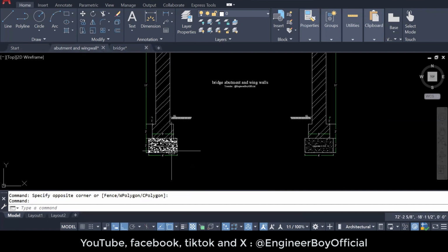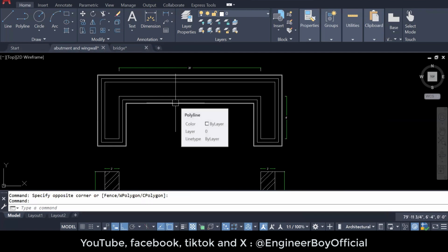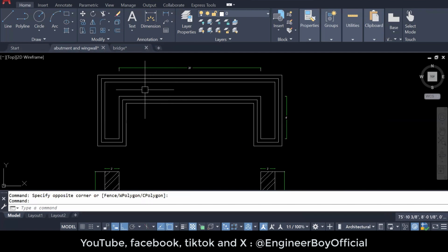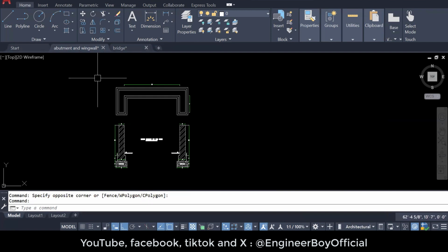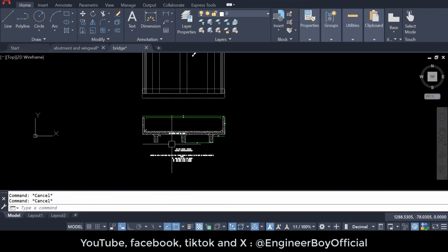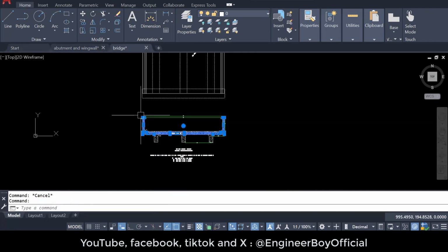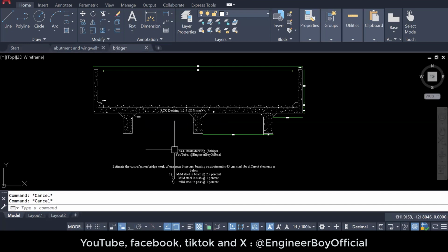In the first stage, we will prepare the abstract of quantities for different materials used in the same diagram. And then we will switch to the bridge decking, which is the same thing, and we will determine quantities of materials, and then of course we will include cost as well. I'm not going to do this on a whiteboard. We will just do it in an Excel sheet because a whiteboard can take much time.